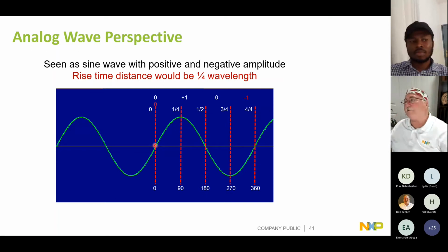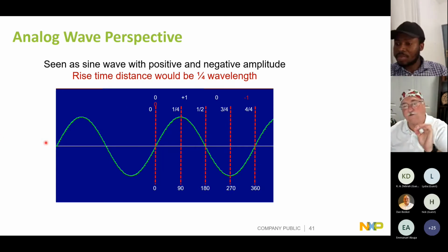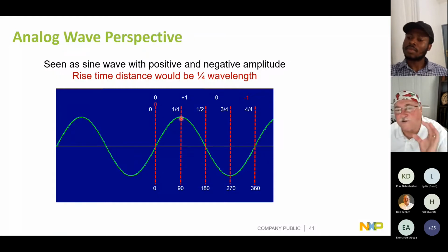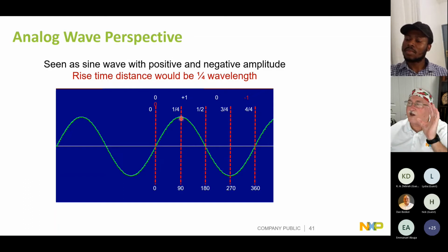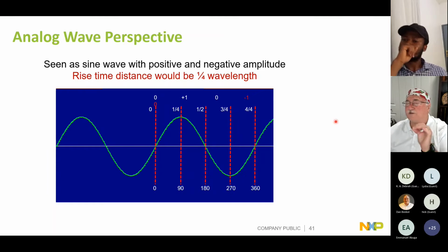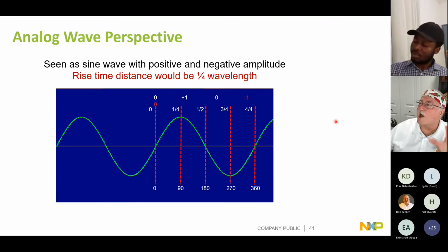So the corners where the energy is applied, and so what the field sees is a gradually increasing impedance until it gets to the end of the quarter wavelength antenna. At that point, its voltage is maximum. So the field presented to this space is the highest it can be. At this point, you're at some impedance that's very, very close to the impedance of free space, which is 377 ohms. So the field doesn't know it's supposed to stop.